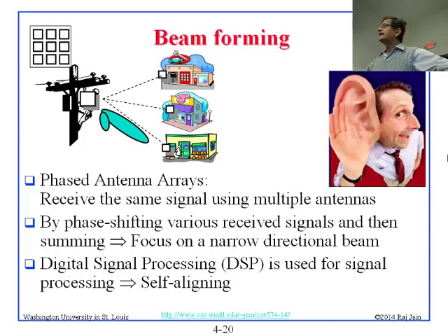Right? And the interesting thing is that all of this can be changed in a microsecond so that it goes to this house without any mechanical movement. It's all an electronic phasing thing, right? It can go to this one and then it can go to that one and it can come back. And they do this. This is called beam forming. So basically, you might think you're getting the signal continuously, but you get a signal for a small time. You're doing time division multiplexing in some sense, and it is coming at a very strong power to you and then going to the other persons.